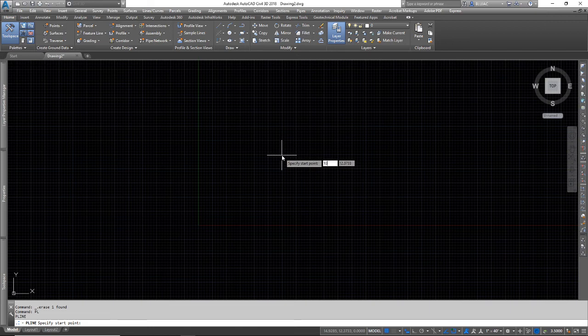I'm going to start a corner at 10, 10, just like we have been. But now let's say my drawing is set to those absolute coordinates, and I want to force relative coordinates, just like we did when we were in the relative coordinate setting and we wanted to force absolute coordinates. We can do the same thing in reverse, but instead of the pound symbol, I'm going to use the at symbol. So shift 2, and you can see next to my cursor it did capture that at symbol, and that's going to force the relative coordinates for my polyline.